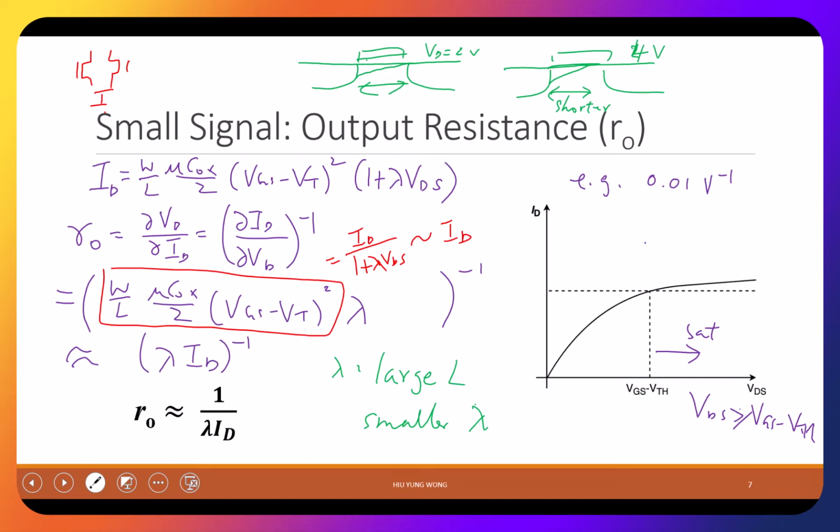So you want to make it larger. Maybe let me make it 100 nanometer or 80 nanometer. Then the original 2.5% error now will become 1.25%. Right? Then it will be easier. This is just because of the fabrication process, right? You draw something with 40 nanometer. After printing, it will just have a lot of variation throughout the wafer and even within the chip.